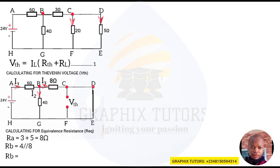So my R_B will now be 4 times 8 divided by what? 4 plus 8. And that will give me 32 all over 12, and 32 over 12 will give us 2.67 ohms. Now what have I done successfully? I have merged the two resistances in parallel. They are now one, acting as a single unit, acting as a team. They are now one, right?